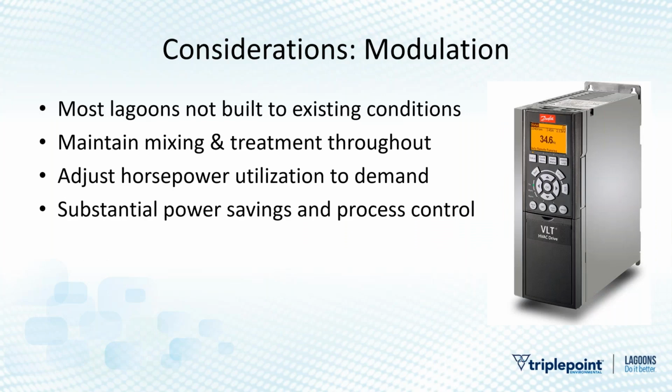Another aeration consideration that's really important, I think, for you guys is modulation. Can I modulate the aeration in my system? Because especially municipally, you're designing for your town, what it might look like in 20 years. You might be growing, but you haven't experienced that growth today. You're going to put all that equipment out there to aerate for, I don't know, 2041 when you don't have those flows and loadings. That means you're wasting money today.